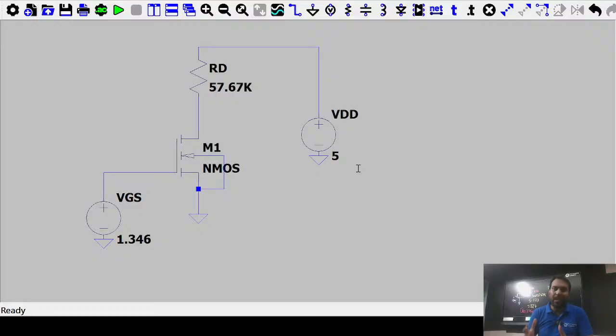In fabrication terms, you have a lot of parameters. When you go for solid state, they just use a block made with the help of silicon and germanium or anything. They are using a material, and they are trying to make an amplifier. So it is not only given ID equal to half mu n COX W by L times (VGS minus VTH) whole square. It is not like this. When you go for solid state or microfabrication technology, you will find that you have a lot of parameters beyond that. It is not only 1 plus lambda VDS, you have a 1 plus gamma and 1 plus something beta and something like this.